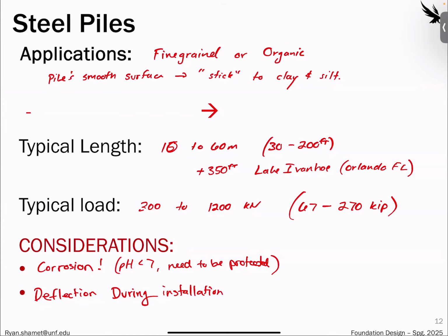Yeah. Do they ever pre-drill some of the driven piles, just to help guide it down straight? Just a little bit of the track out, so it goes down a little easier, keeps it on track? Yep. For driven piles, you would clear past utilities, so the backhoe would come in and usually clear the entire bent that you're driving your piles in, not each one individually.